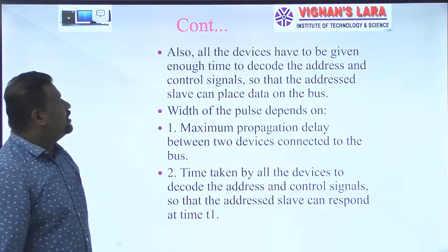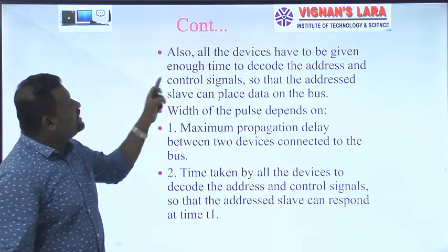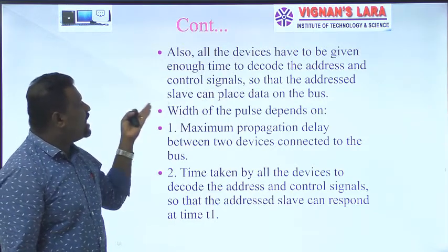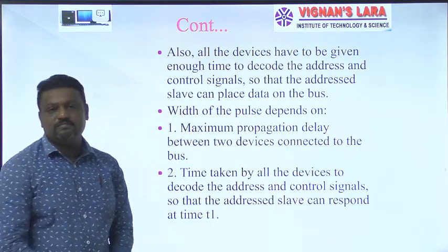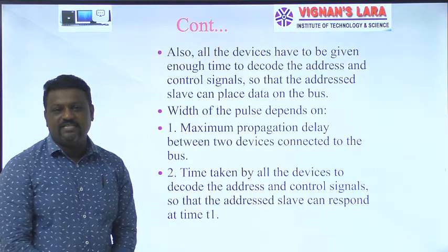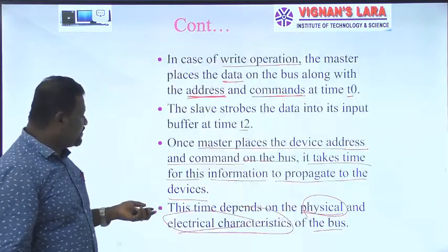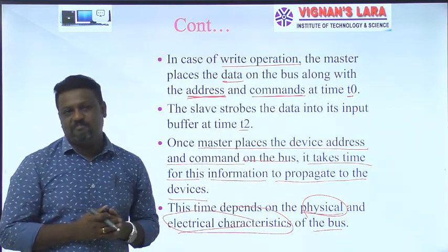All the devices have to be given enough time to decode the address and control signals so that the addressed slave can place data on the bus. This is the second case. From this onwards, I am focusing on how to do a read operation.